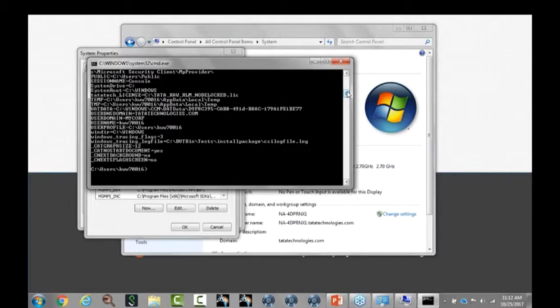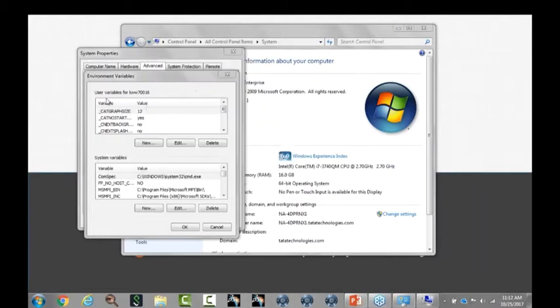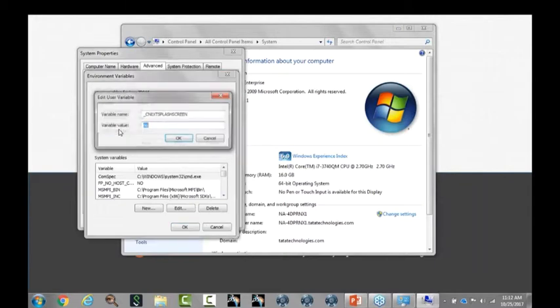Well, you can put these variables that we're going to talk about into that particular file, but most of you probably do not have access to do that. So you can set up what are called user variables or user environment variables. The one that we're going to deal with first, I'm going to edit the cnext splash screen. Remember, cnext is the name of the executable. And I have just put an underscore character at the beginning so that they become inactive.